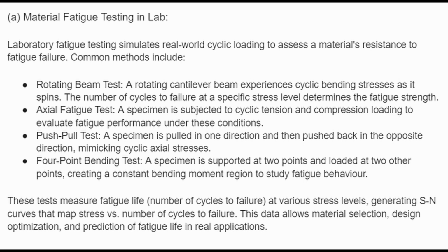B. Axial fatigue test. A specimen is subjected to cyclic tension and compression loading to evaluate fatigue performance under these conditions. C. Push-pull test. A specimen is pulled in one direction and then pushed back in the opposite direction, mimicking cyclic axial stresses. D. 4-point bending test. A specimen is supported at 2 points and loaded at 2 other points, creating a constant bending moment to study